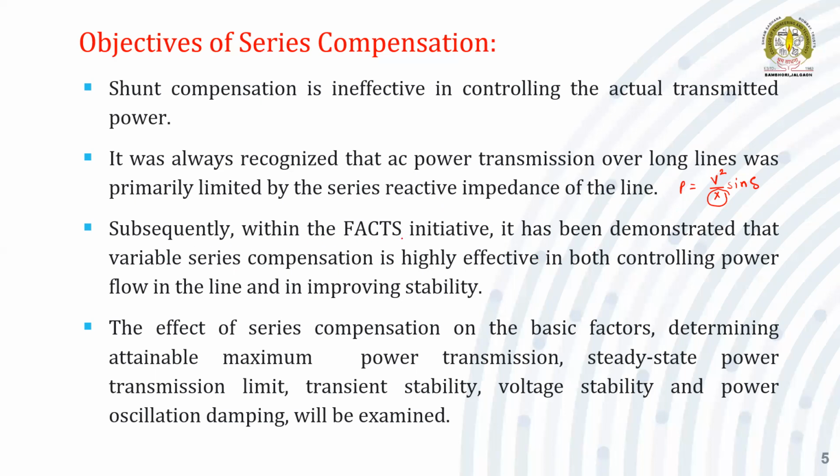Now, subsequently, within the FACTS initiative, it has been demonstrated that a variable series compensator is highly effective in both controlling the power flow in the line and improving stability. When we go into the details of the series compensator, we will definitely come across that not only the power handling capacity, we can very well control the power and improve the transient stability and voltage stability with the help of the series compensator.